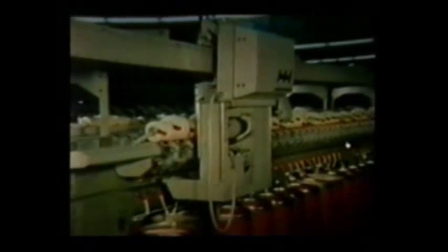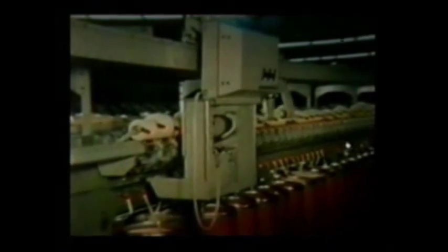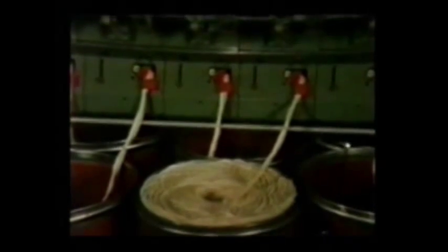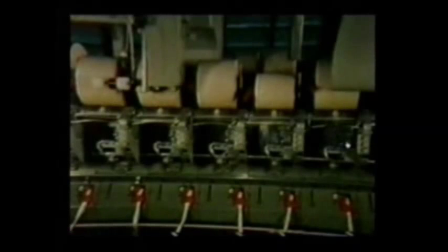Here is the piecing action, as you can see, where the yarn is being pieced. Also, you will see later on in other video clips the cleaning action. Here is the winding head, and you can see how large this package is compared to the small bobbin that we have seen in ring spinning in the early video clips. Major development, as you can see here. It's very important to keep these points in mind.